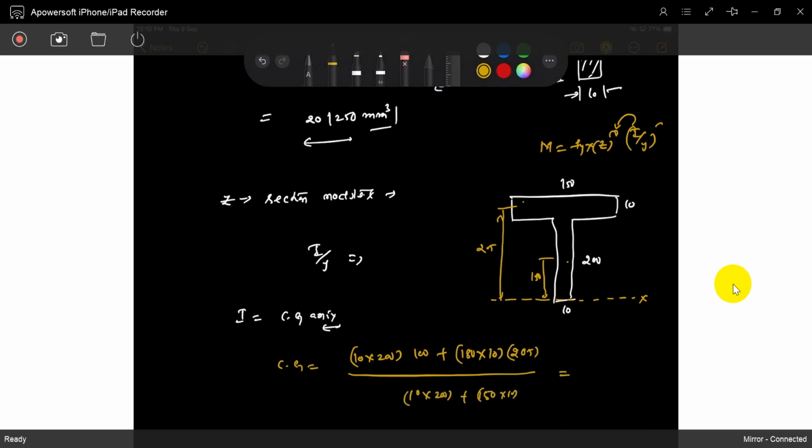So what is that value? That value is the total 210 minus 65, which is 145. You will get 145. That is the CG axis, 145 from the bottom. So the top is 65, total 210. That is the neutral axis for elastic analysis. This is the CG point, exactly the center of gravity.